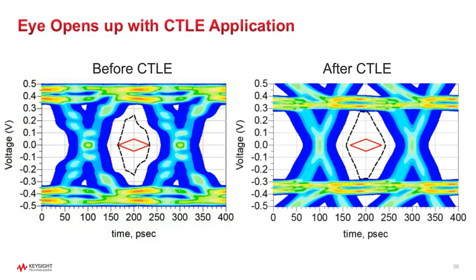But just based on what I used today, the controlled impedance line designer, you don't have to specify the ports because it looks at the 2D cross section, the width and the substrate height. Based on that, it gives you the impedance, differential and common. Let's see, I see the odd or even. It gives you all the information, but what we really care about is differential impedance and common impedance for the differential pair. Thank you. Great.